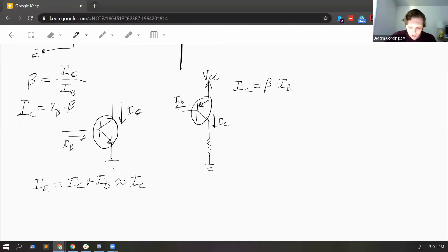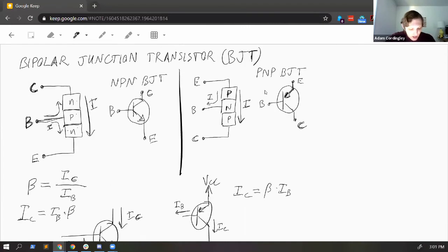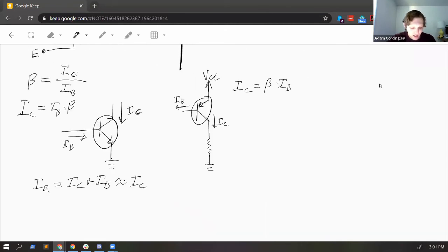Before we move on, just worth noting, because you have this PN junction between base and emitter, the current through it follows the Shockley diode equation, just like a silicon diode. Just like a silicon diode, you have this 0.7 volt junction, or if you have very small current, you have a very small voltage there. But for any appreciable current, above a few tens of microamps, perhaps, it'll start to converge at between 0.5 and 0.7 volts.